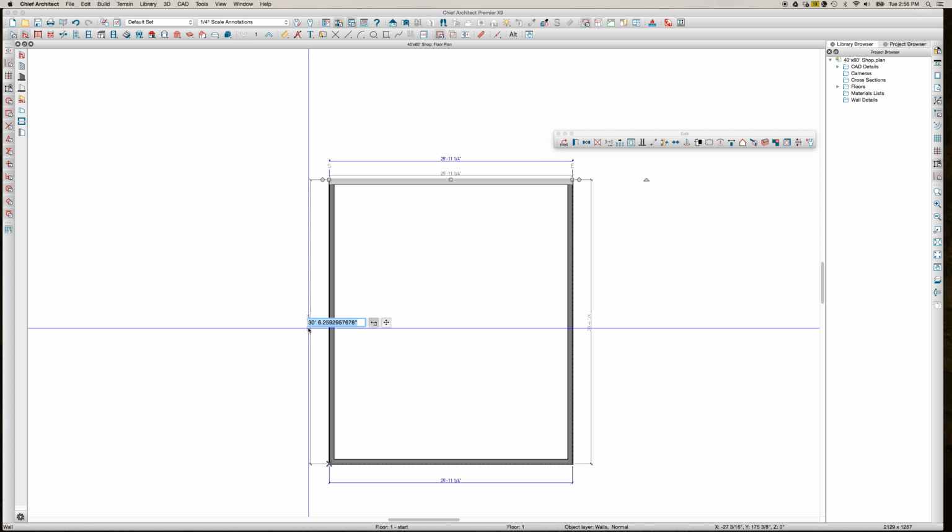Now we'll add a foundation below this. Because it's a shop, there's not a whole lot of detailing that goes in with the main structure, but we'll create a 6-inch slab here. The default wall that I have set up is good, but I'm going to change the footing width to 24-inch, wall thickness of 8. That'll work just fine. When I click OK, we will derive new foundation plan from the first floor, and boom, there we have a